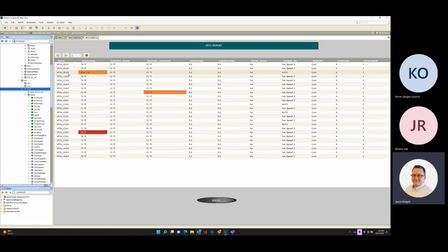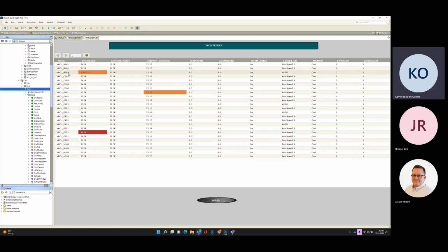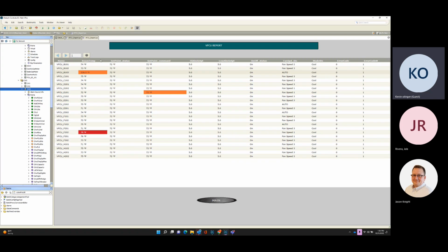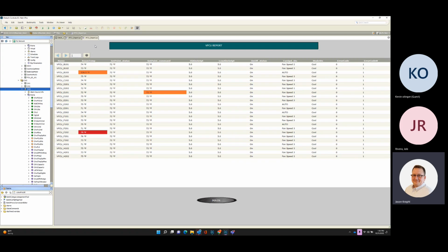It was the normal schedule that was overridden from the graphic, so all the fan coils associated with DOAS 6 were overridden on. And that kept DOAS 6 on because the fan coils were on. Yes, so it's kind of the self-licking ice cream cone happening.